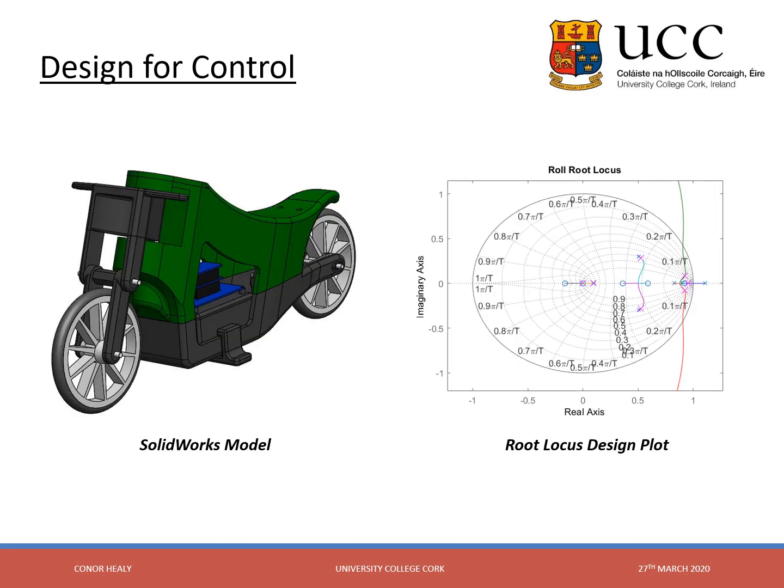The motorcycle was designed to the specifications discussed earlier. Properties such as center of gravity and overall mass were exported to MATLAB where controllers were designed using root locus plots. The root locus is a design tool used by control engineers to help place poles and zeros to give desired controller performance. Of particular interest are natural frequency, damping, and settling time. The root locus also allows control engineers to check the system for stability.